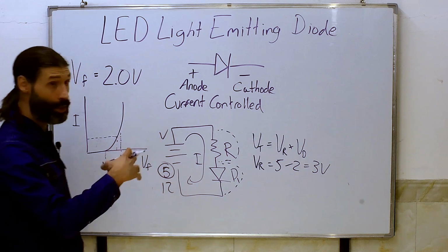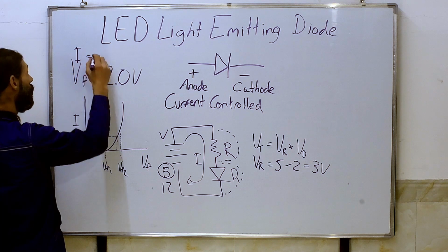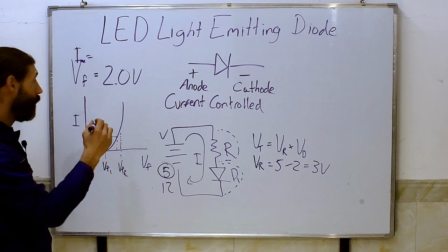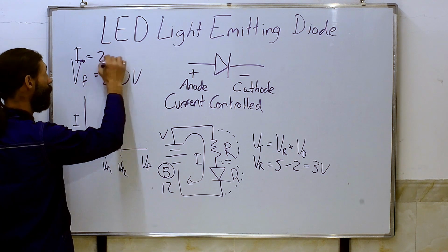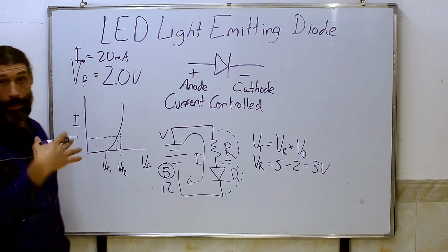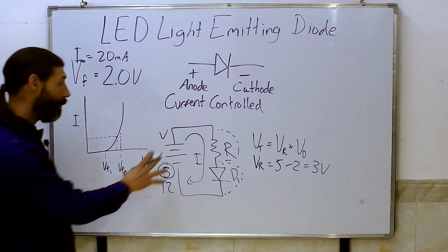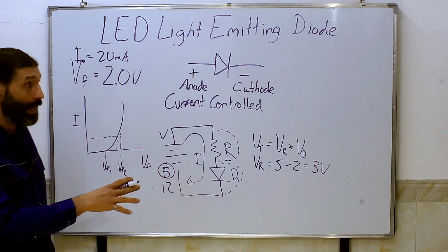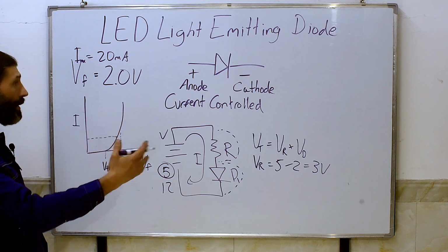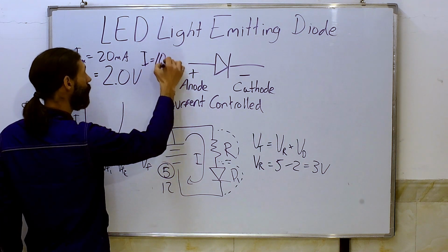And this goes back to the data sheet. Where we found our forward voltage for our LED, we're also going to look up the current. The maximum current is given in the data sheet, and for a small red LED, it'll be something like 20 milliamps. Now, there's no need to run it at maximum brightness most of the time. It can shorten the LED life, but also this is an approximate calculation, and it's not necessarily going to give us exactly 20 milliamps. It might give us 21. So let's err on the side of caution, and let's use I equal to 10 milliamps.